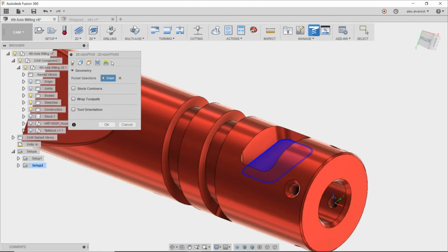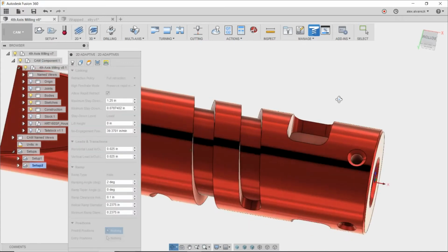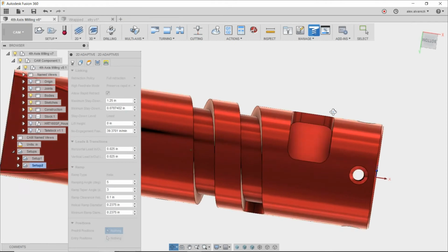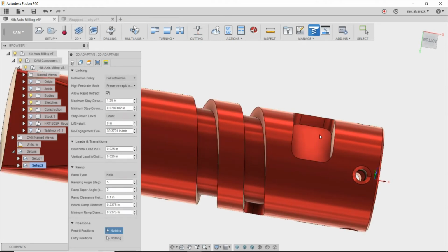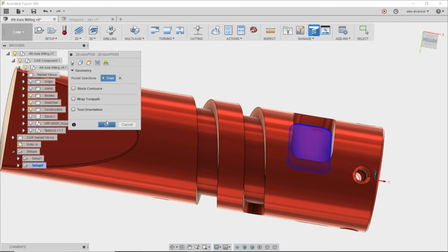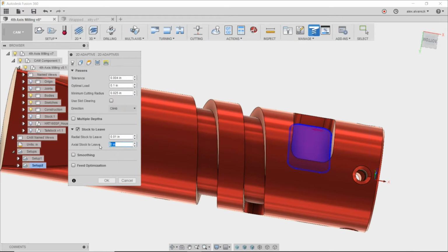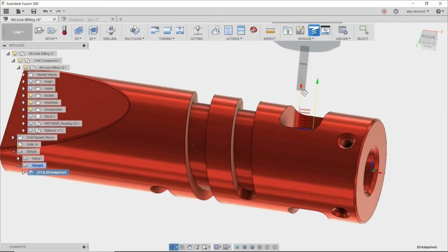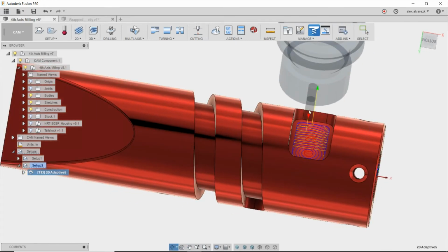It is going to be machining pretty deep into this material, so you can add some sort of ramping as well as taper to your ramp. That's going to provide better chip evacuation, and you're not going to have chips cluster right here as you start machining lower towards this part. So that looks good. We can leave some material both on the wall of the part and on the floor, and we get the appropriate toolpath there.